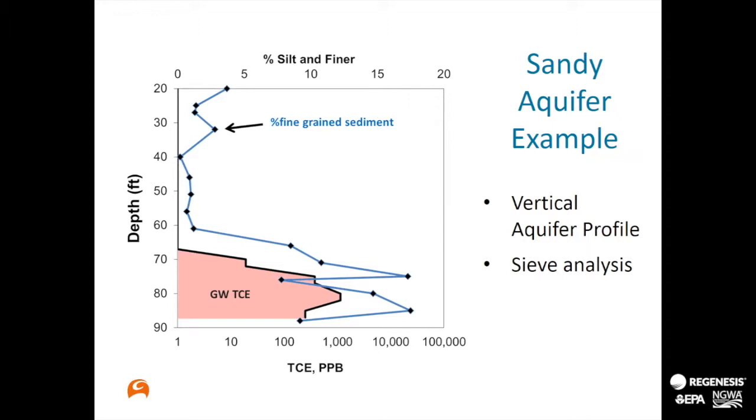So what we're realizing is the back diffusion question is not only a clay-sand question, it's a higher versus lower K question, and the contrast of 100 or more, based on Beth Parker, we think holds true here. A contrast of 100 or more means you're into that territory, but this is a solvable problem because we can induce vertical migration.